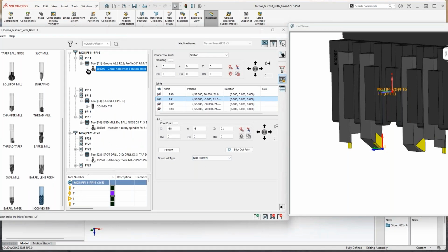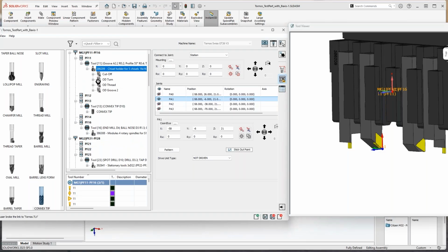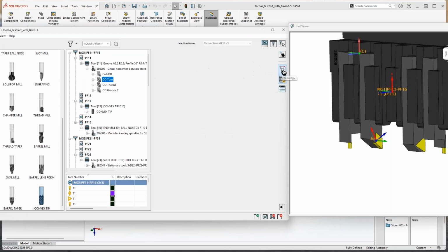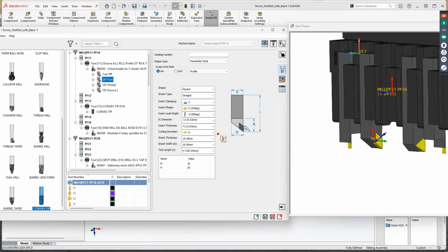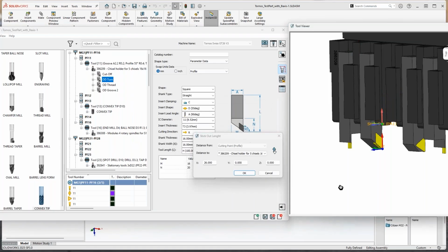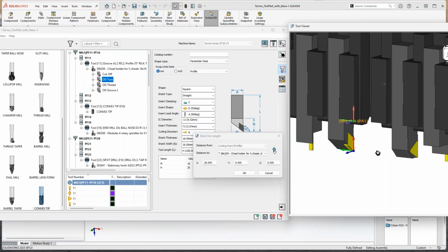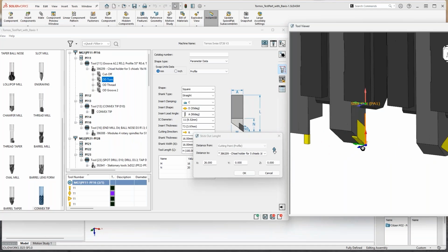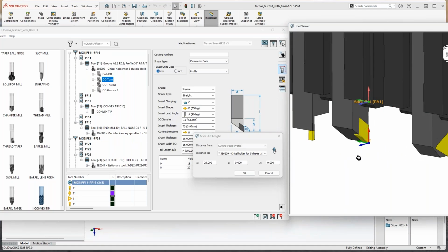But how can I affect it? So I can click on my cutter over here, and I can go now to the topology. And now, for the first time, we added a new icon located over here. So you have an icon that can control where your tooltip is, and you can click on this. Once clicked, we'll show only related coordinate systems. Not like in the previous versions, where this positions actually took a lot of coordinate systems, and that was a lot of mess. But now we just show you the most relevant coordinate systems here.